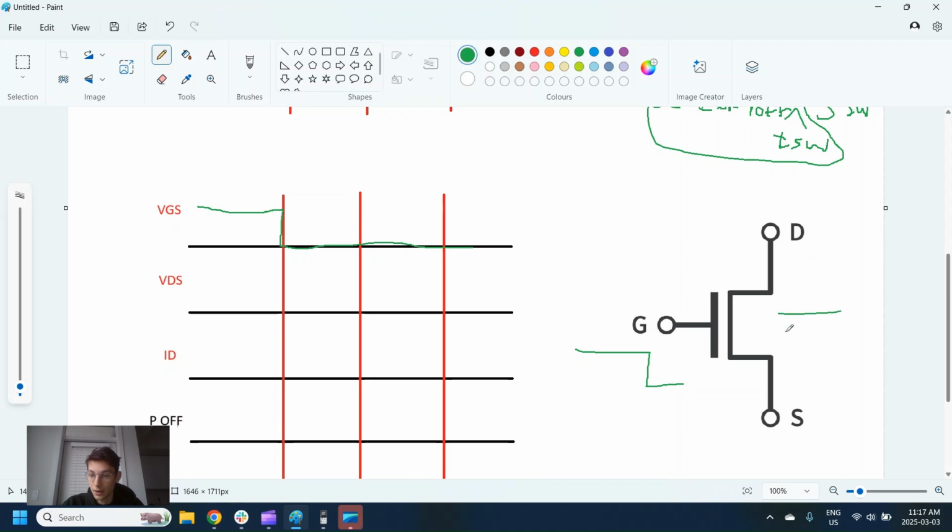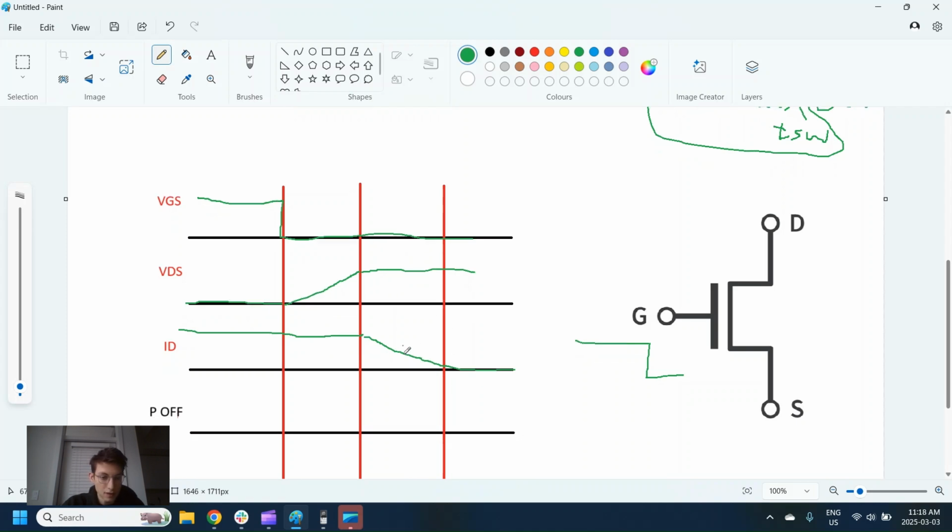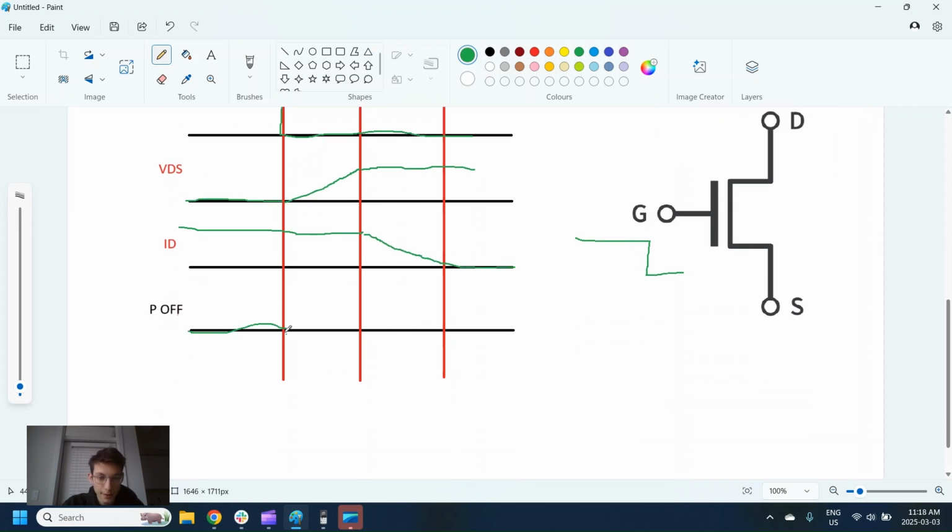When we currently have it on, we're pushing current through, and we're trying to open it and let no current through. In this case, we see it's the voltage that first has to ramp up. So the voltage ramps up, then stays open, and the current is the one that lags and drops off after. That gives us our same sort of triangle here.